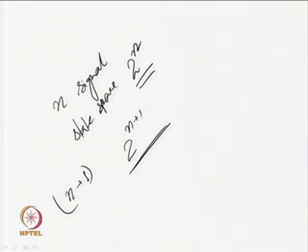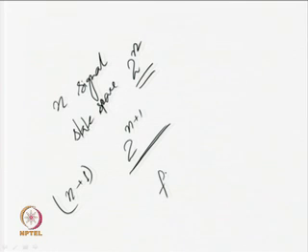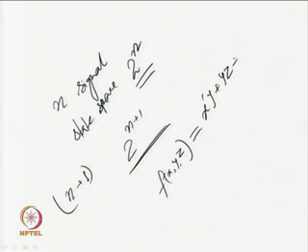What is BDD? It is a binary decision diagram, which is a data structure to implement or store any Boolean function. If we have a Boolean function of 3 variables x, y, z, then the function f(x, y, z) can be represented with some Boolean expression, say x bar y plus y z plus z x bar. Such a Boolean expression can be stored or represented with the help of a binary decision diagram.